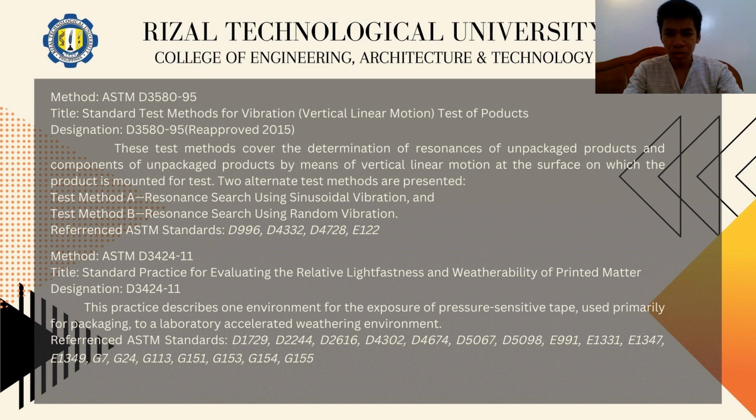Products are exposed to complex dynamic stress in the transportation environment. The determination of the resonant frequencies of the product may aid the packaging designer in determining the proper packaging system to provide adequate protection for the product, as well as providing an understanding of the complex interactions between the components of the product as they relate to expected transportation vibration inputs.